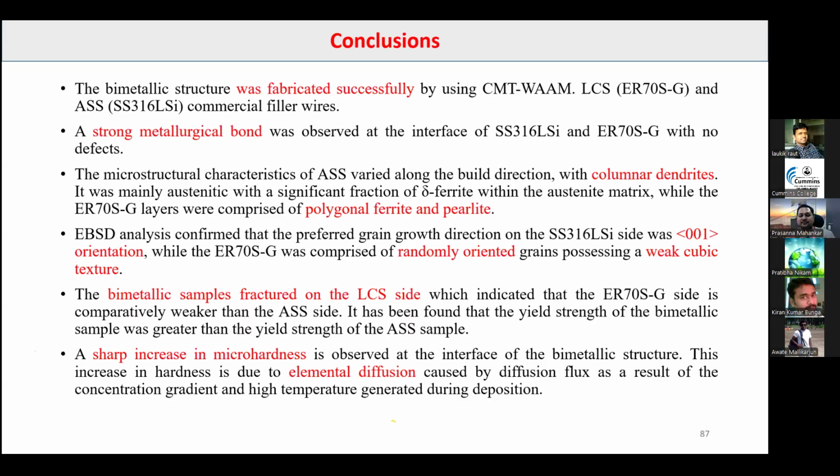Yes. And Raut sir, sorry to interrupt. You may please go ahead. Yes, sir. As you told previously, we can combine 2 to 3 materials at the same time. You were saying we can go layer by layer, or make a composite and then deposit the beads? Yes, even layer by layer we can deposit. Now people are depositing one layer of, say, steel, another of nickel, again steel, then nickel. Right now people are depositing like that, because in every layer you get different properties. So depending on the application, you can use that material.